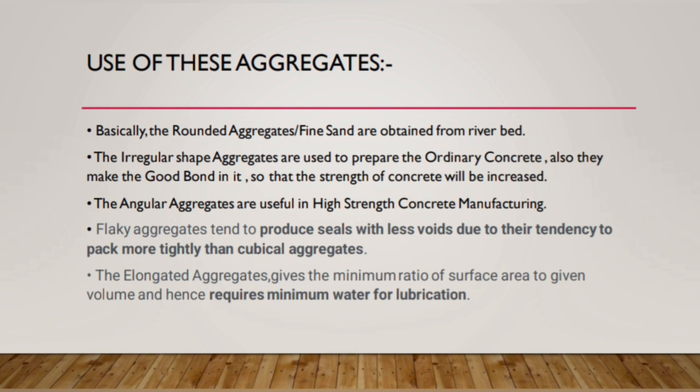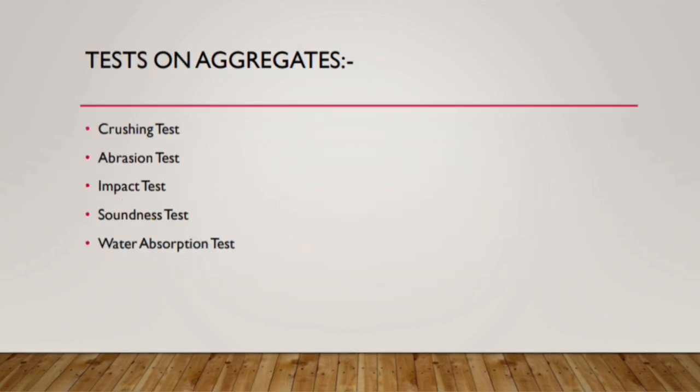These are some of the points which we discussed. Different tests on the aggregates: the crushing test, abrasion test, impact test, soundness test, and water absorption test. Now we'll see the main 3 tests which are carried out on the aggregates.